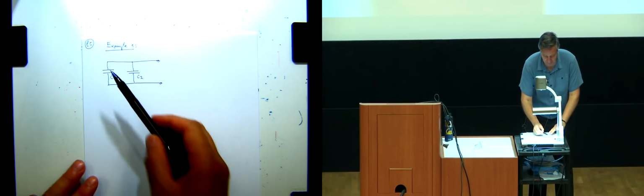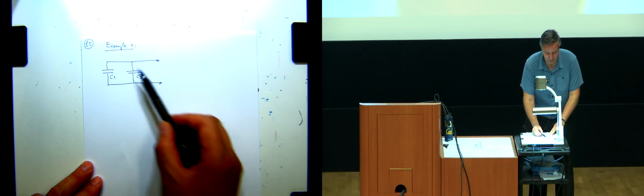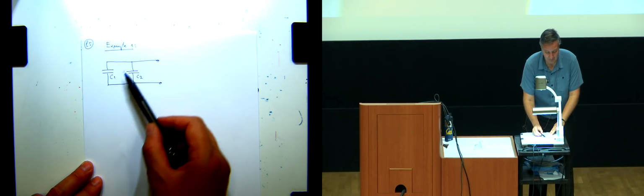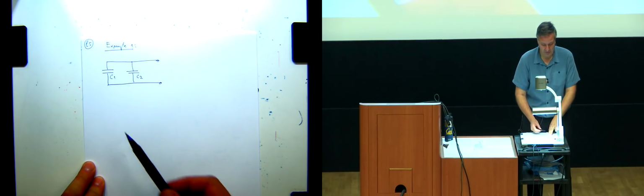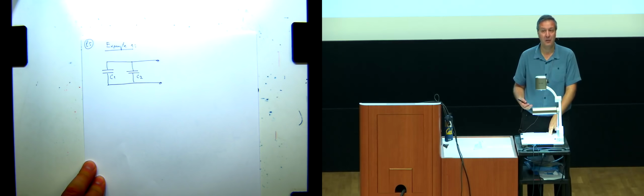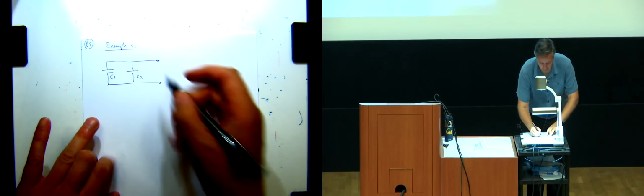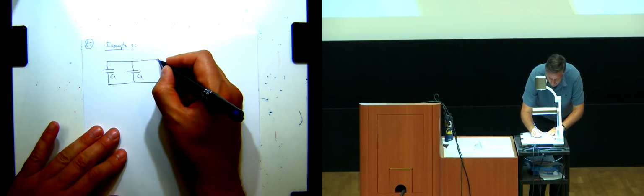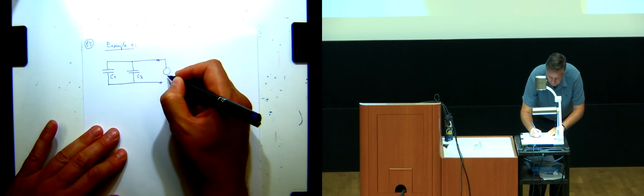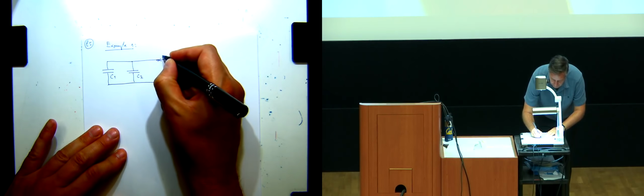Okay, so you're saying that applying voltage here would be easier because both of these capacitors have the same voltage across them, right? So this is one node, this is another node, right? And in other words, they're by definition in parallel, right? So when they're in parallel, applying a voltage source is easier, right? So let's do that. We want our life to be easy, not hard. Okay, so this is dV test dt. This is going to be I test.